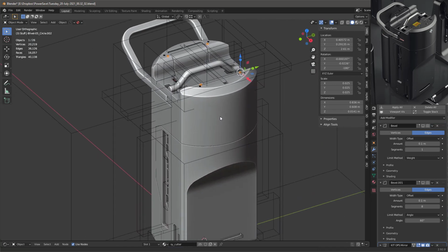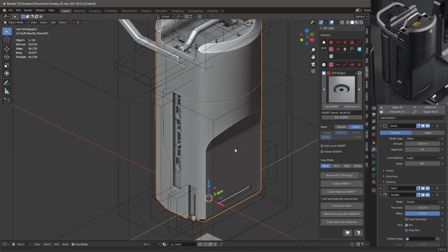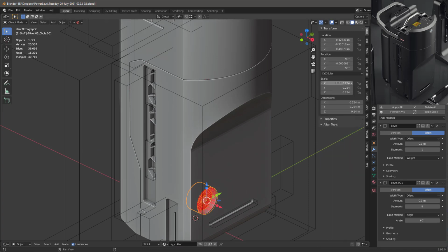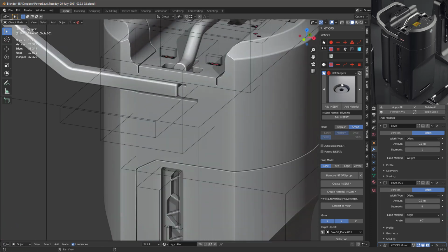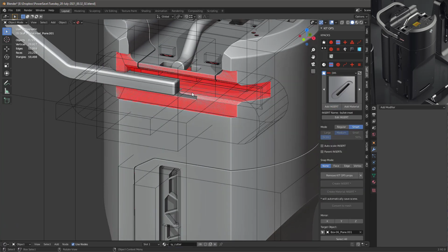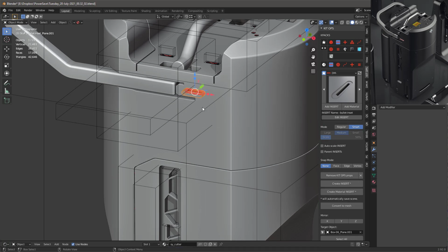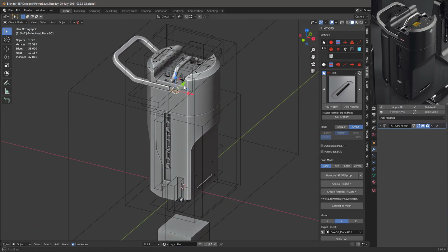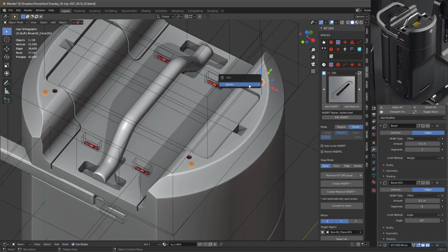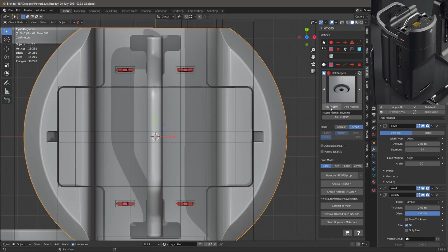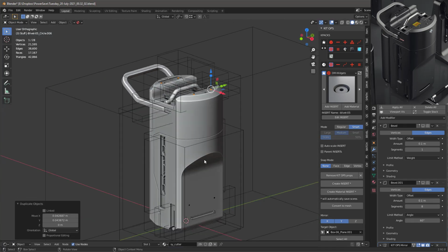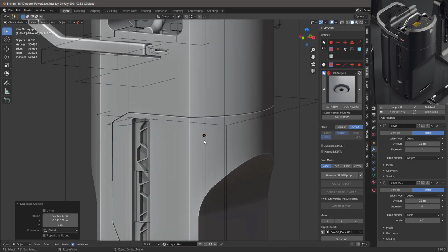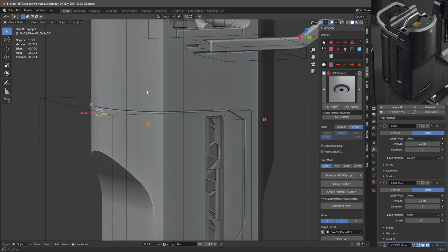And I've gone in, I'm going to copy the actual scale of that one, so I make sure I get them all the same. So I'm dropping this one in here, and I'll just go into scale, and I'll just paste it. So I know I've got the same one there, mirror it, and then I'm going to add this little slot detail in here. And these, I realized they were wrong, so let's go ahead and add them again. Drop them in. And we Shift D and move them up, and they're mirrored. And we add another one right here on this side.